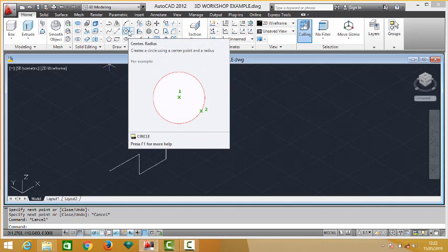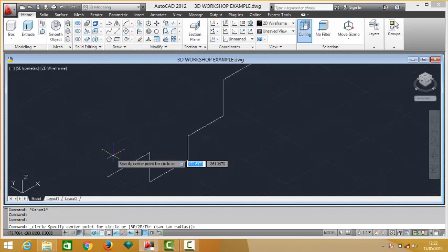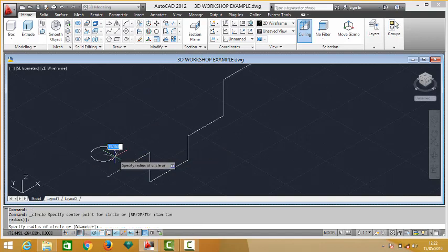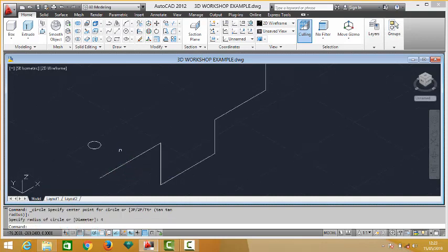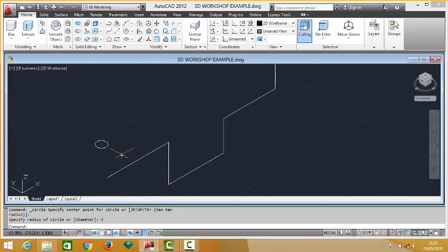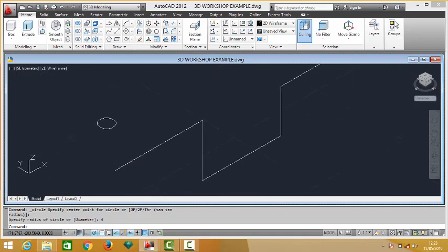and then let's get at our circular profile with which we will use to sweep. Now let's take a circle of radius 4, that is diameter 8. So enter. Now we should be very careful that the radius of our circle is known, because from the radius of our circle, which is 4, and of course if radius is 4, we have diameter 8, we can properly design the thickness of our piping plates.